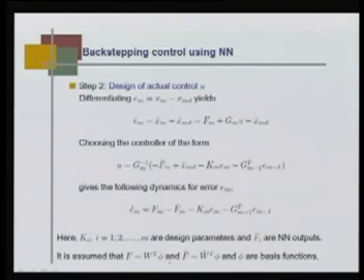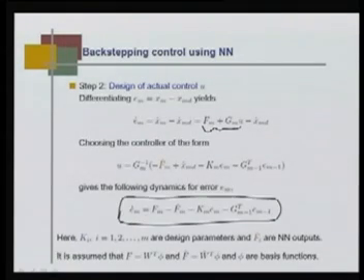After we did that, the last equation em is given by xm minus xmd. Its time derivative is fm plus gm u minus xmd dot, because xm dot is given by this quantity already by the strict feedback form. Choosing u is again found using the Lyapunov function approach, when we assume that fm is known. Then this is the control action that will stabilize, so this is my final closed loop error dynamics.